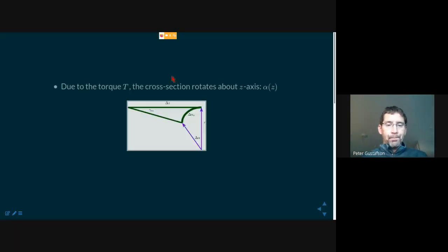Okay, and just to remind you, if I'm twisting only a small portion, it twists less in total displacement than if I'm twisting a long section. That's what we're talking about here, the amount of actual twist. You need to interpret this as a rate of twist, a rate of displacement per unit length in the Z direction. So what's interesting is if you look at this geometrically, there is now a relationship between the shear angle gamma and the amount of twist that occurs.